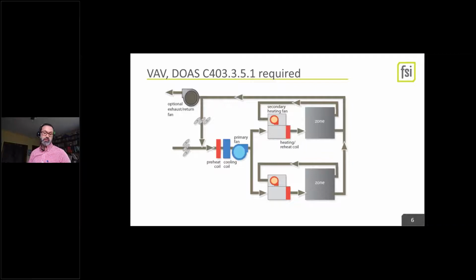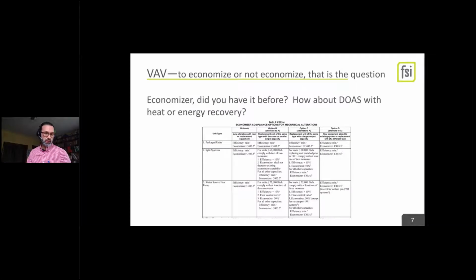It might be easier to change out, but again, the heir apparent is going to be variable refrigerant flow with a DOAS unit and reconfiguring your system. And that DOAS unit ideally would be a heat pump, not with gas preheat. So you're set up for an electric future. All right. Duane mentioned this briefly, I'm going to mention it again.